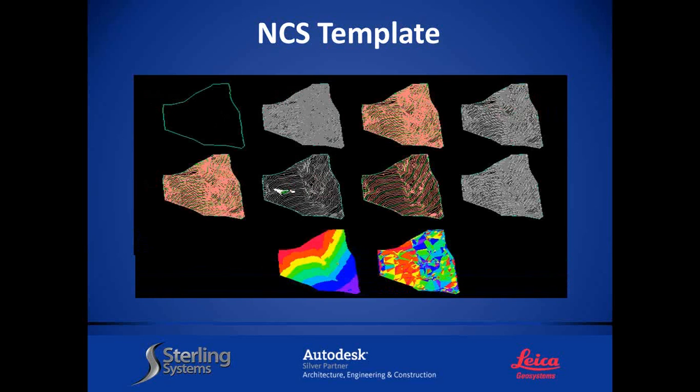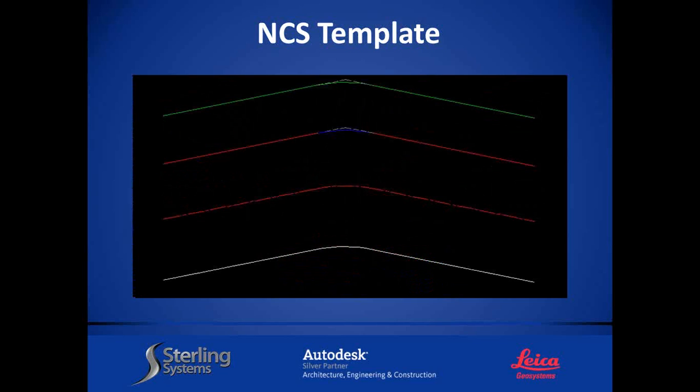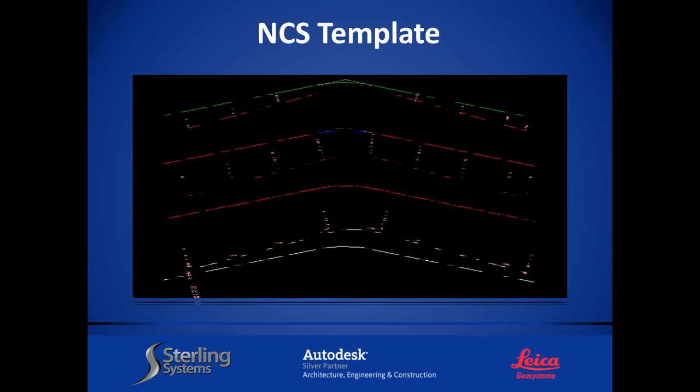All right, so surface styles, this is it. You can do borders. You can do contours. You can do 3D lines with contours, highest, lowest elevation, and highest, lowest slopes. We can blow that out of the water, right? We can do watershed styles. We can change the colors, the contours, the intervals of the contours. We've got to take this to the next level, though, and we have to turn this into our company standards and styles.